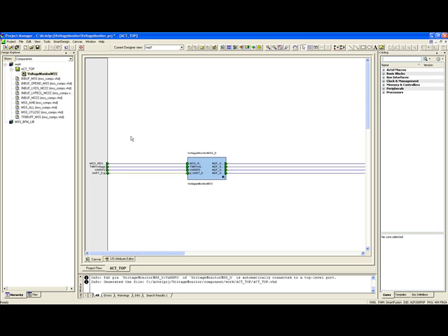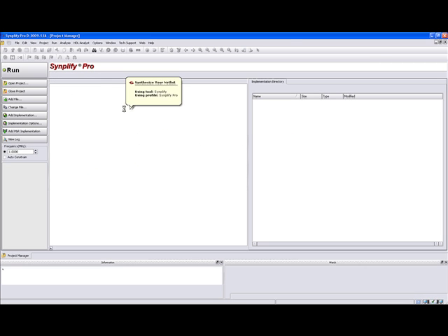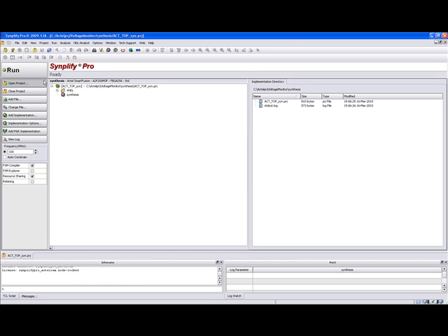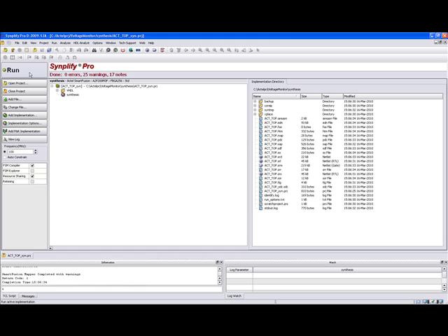Click the Libero IDE Project Manager tab. Right-click ACE Top in the Project Explorer and select Set as Root. Then on the Project Flow tab, click the Synthesis button. Synplify Pro opens. Validate the project settings and click Run. Synplify Pro completes the synthesis within a few seconds. Close Synplify Pro when done.